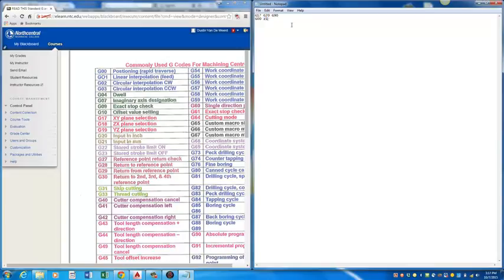Basically, to give you the short explanation, we're going to be programming that machine for Z0 to be touching the paper. So Z1 will be lifting the pen up on those trainers. Okay, so we have G00 Z1. So my pen is up.